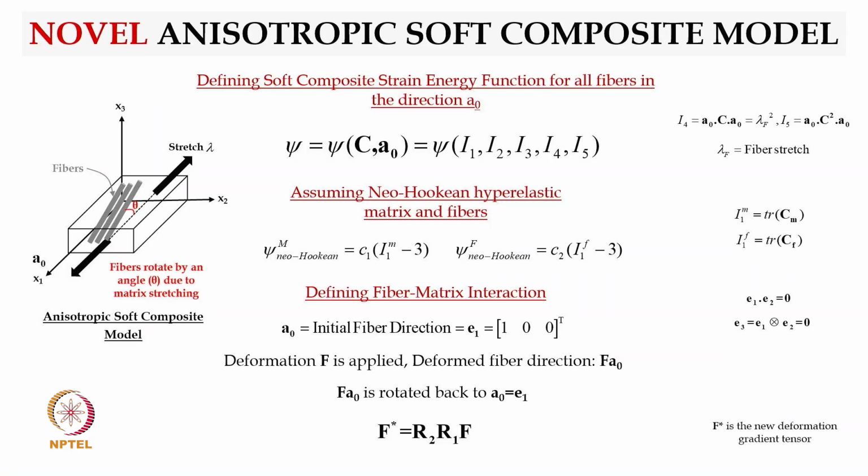So let's keep going. Here, like in the transversely isotropic model, we are now assuming the fibers and matrix each have a different isotropic material property by itself. So fibers are considered a different isotropic material, and the matrix is considered a different isotropic material. The way they interact and are put together within a composite causes the nonlinear, non-isotropic or anisotropic response, right?